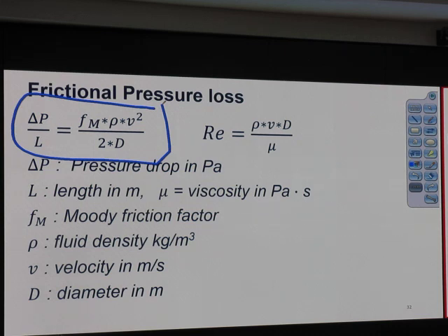We have to turn on the pump for a while, then that equation applies, right? Right at the start, it's not that equation. Got it? So transient includes start, stop, change in the flow rate. Anytime that there is a change, that equation doesn't work. But it is an asymptotic line. After a while, it will reach that point.